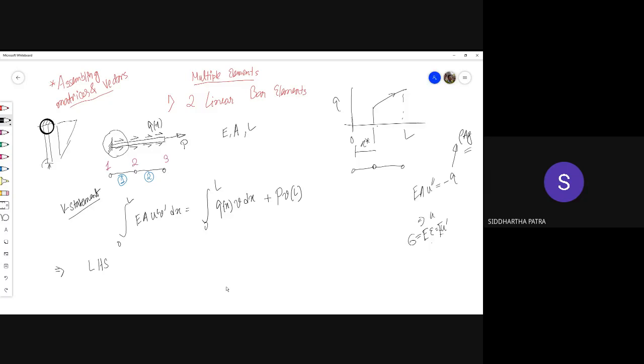The fact that the stress at this end would be zero is one of the boundary conditions. There are two boundary conditions. The first one being u(0) is 0, and the second one being EA u prime equals 0, since there is no concentrated force over here, it's a free end. E times u prime represents the stress, u prime being the strain. So this region is traction free, or for that matter stress free.